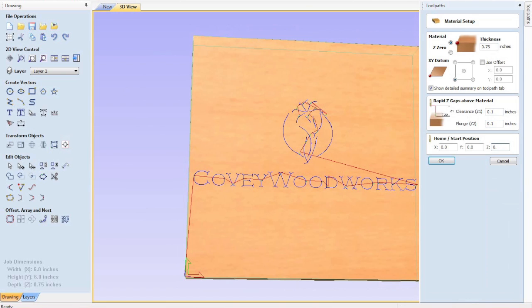This should always be 0. So this is the 0 point. When you set the bit to the surface or where the XY is going to be, it's going to use that surface, or you can create an offset. So wherever you set it, it's going to automatically set however much you want above that. So if you set it to the workpiece top and you want the Z to be automatically set 0.01 below that, or 0.1 below wherever you set it, you can set it right here, and it'll do it automatically. So if you bring your bit to the surface of your workpiece, set it off.